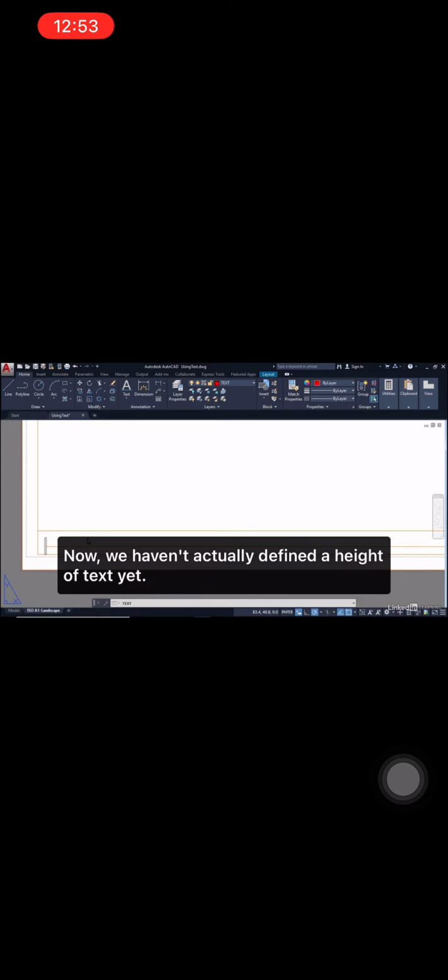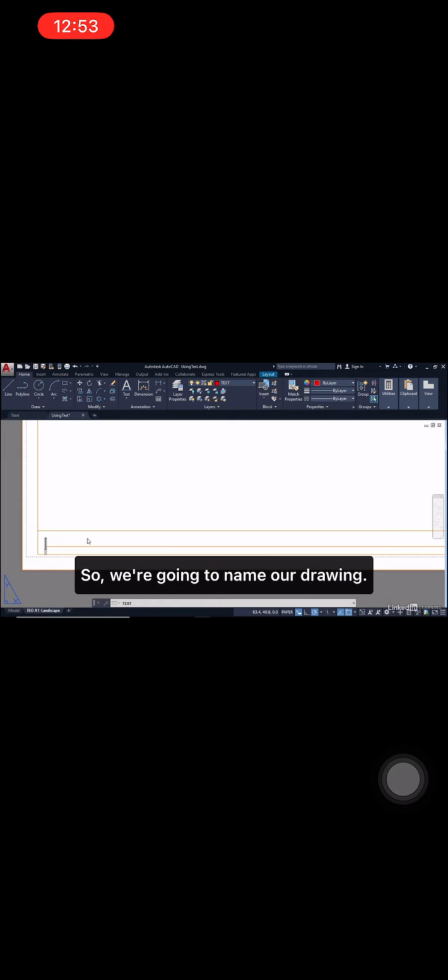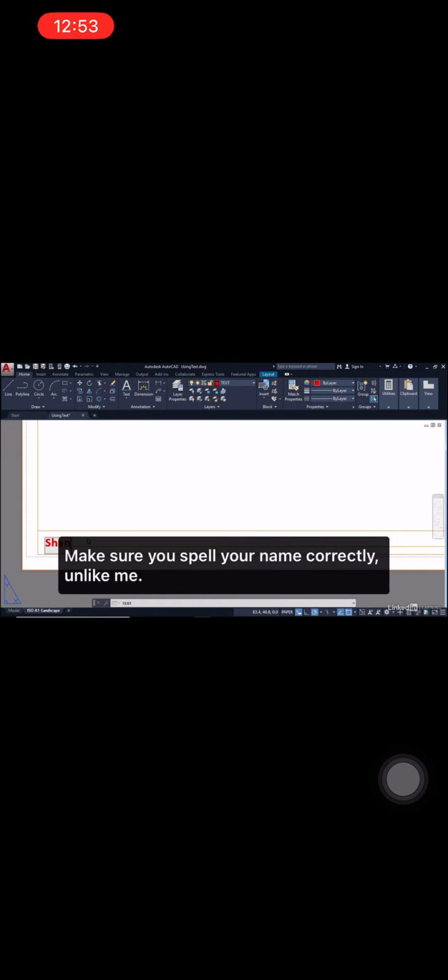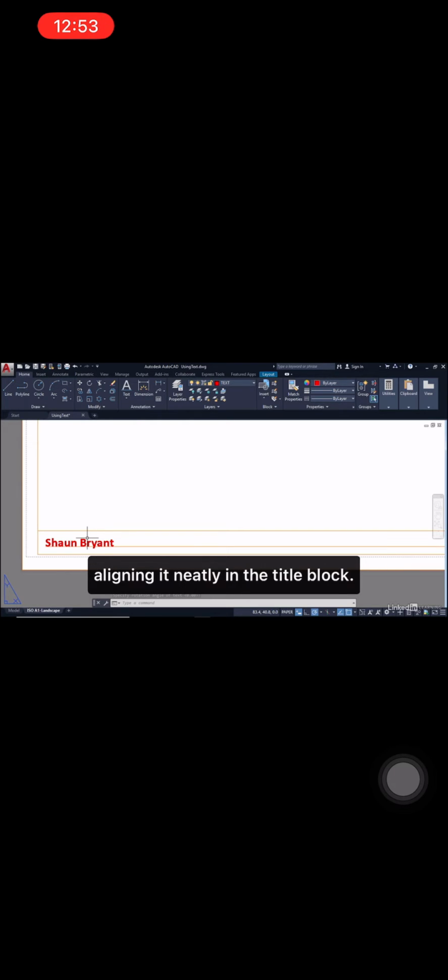Now, we haven't actually defined a height of text yet. Don't worry too much about that. What we're going to do is put our name in there. So we're going to name our drawing. Make sure you spell your name correctly, unlike me. There we go. So Sean Bryant there. I press enter once, and then I press enter twice. And you'll see that that's placed that text nice and neatly on the left-hand end of the line, aligning it neatly in the title block.